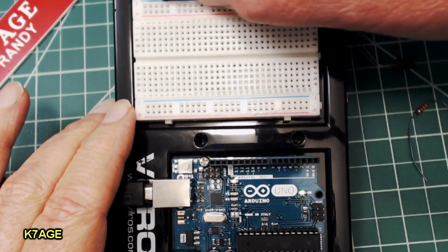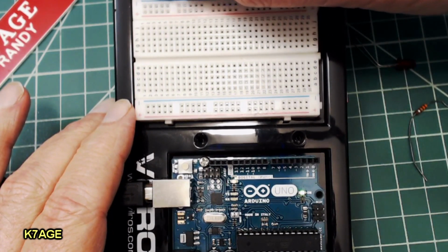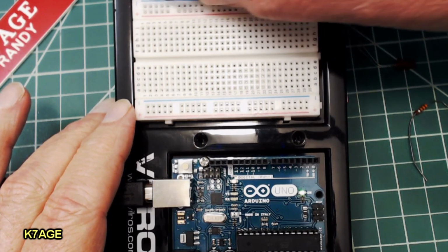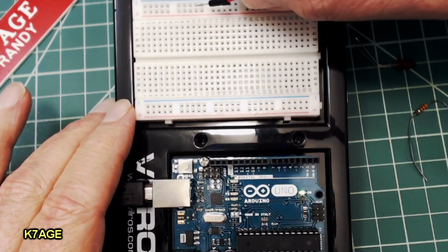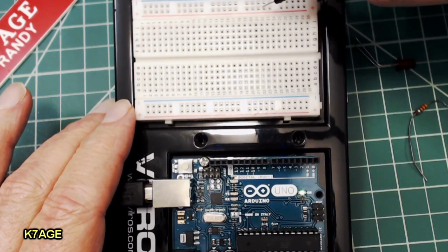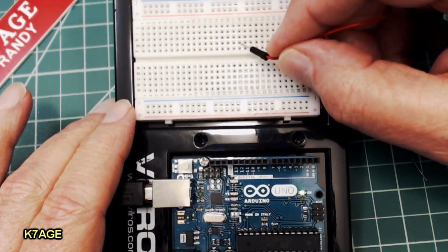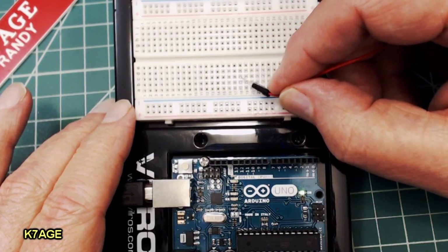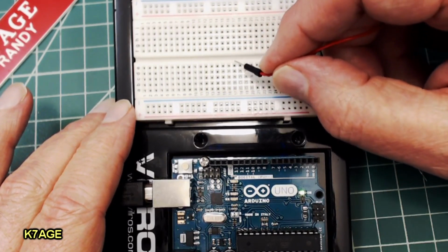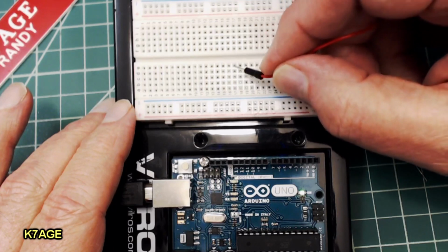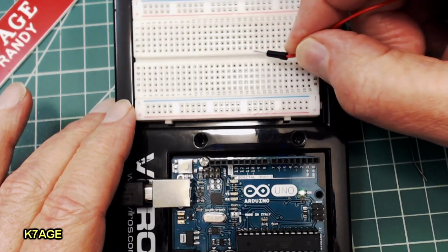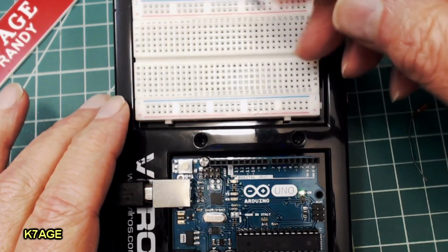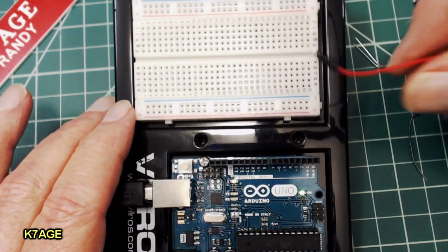The ones down the side here, these are connected all the way down the board, and these are labeled minus and plus, which is where you can hook up jumpers to the power supply voltages to have those buses. Now the pins on this side of the board are separated from the pins on this side. So an integrated circuit can span across the junction here. You could have 8 pins down this side and another 8 pins down that side. But we're just going to use a jumper wire here and the LED.